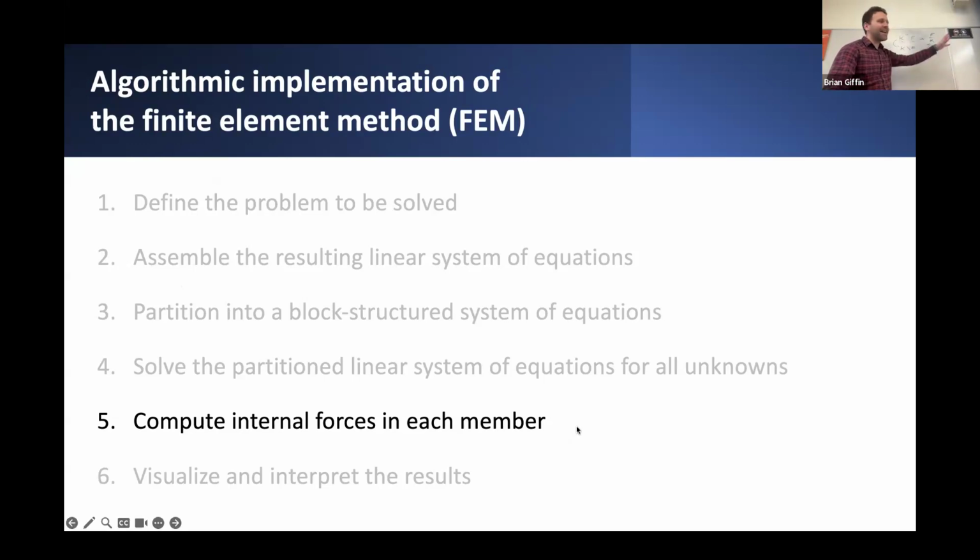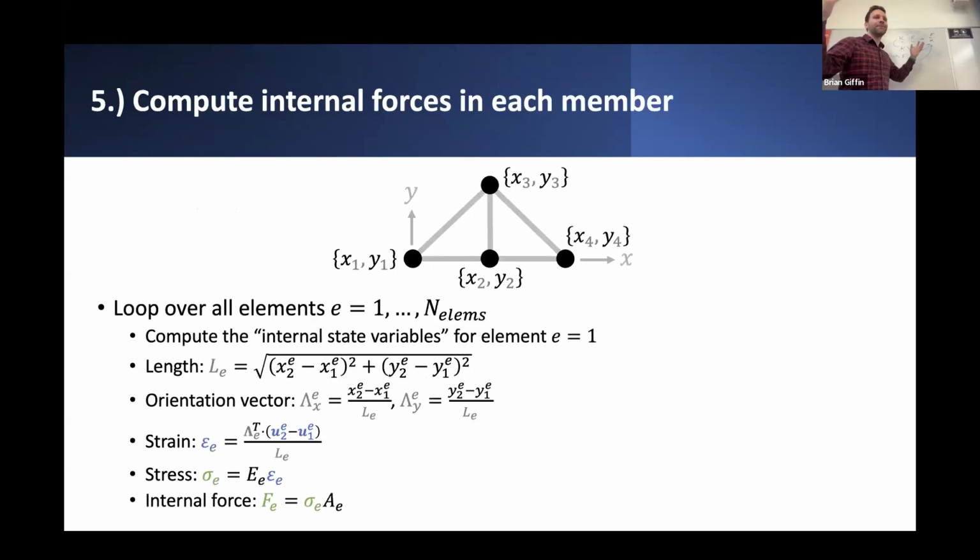All right, so once we have that, we've solved for the displacements of the structure, but that's not really the thing we're interested in. If we're trying to analyze the structure and maybe design the section sizes for the individual members, what we want to know is the internal forces in a given truss element.